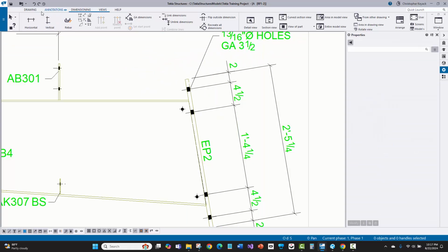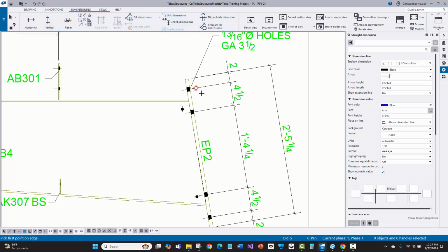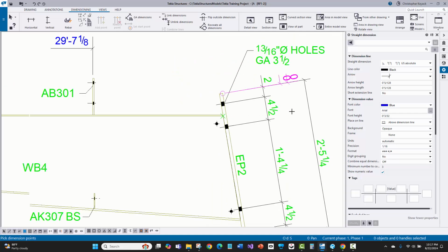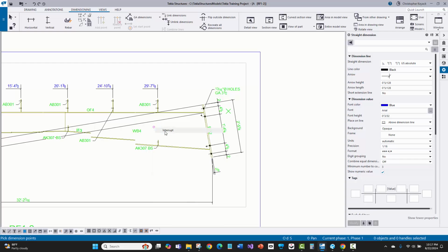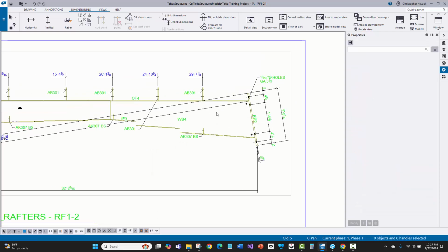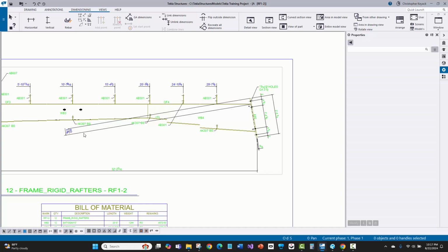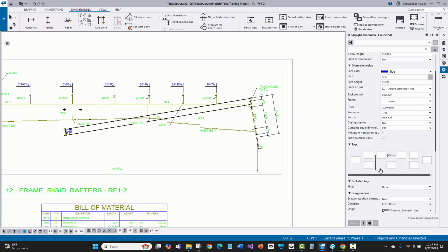And again, if I just go back to dimensioning, I'll do parallel dimension here. I'll just click two points to define along that axis. And then I actually picked the wrong point there real quick, but let's just do that, and middle mouse button. Now, if this happens to you, sometimes I love when mistakes happen, because then it shows people, hey, what's going on there? Why did that happen? Well, the reason this happened is because there's this fixed property.